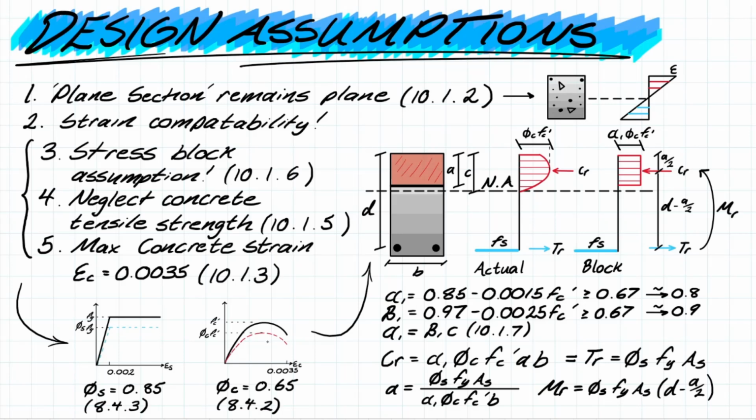Now, looking a little bit closer at the stress strain profile for the concrete, we can actually notice something because we transfer this factored curve over to our block in our problem here. So this stress strain profile is actually representing the exact stress strain profile for our concrete member as well about that neutral axis because we assumed that the strain is linear. So we can directly take this graph of the stress strain where the strain is increasing linearly and transfer it right to our problem. But there's a problem here as well.